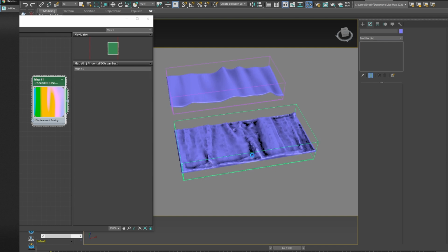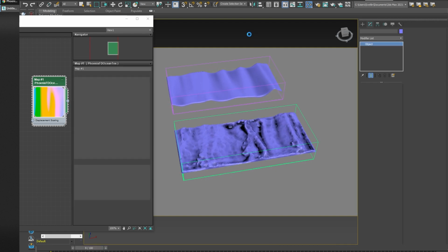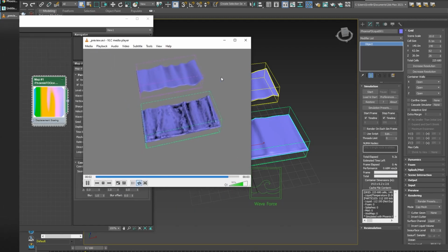I'm going to just record this, and this is something that you should always start with. So I'm going to check if the speed of the ideal ocean wave is right. So you can see that we have that simulator which is 26 meters tall, and the ideal ocean wave, the pure ocean, is moving at this speed, and this speed is way too fast. So waves that are like 10-15 meters tall that would fit into this 26 meter tall simulator, they won't be moving with this high rate.